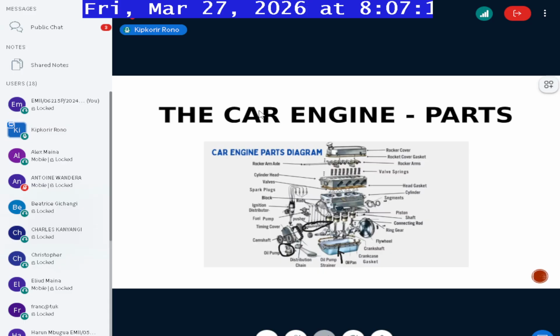Number two is that the oil usually settles at the bottom of the engine. Okay? With the oil reservoir. So if you were to just switch on your car and move, some parts of your engine could be oil starved, all right? That oil starvation is not very good, okay? So you usually have to let the car allow the oil to circulate for a few seconds or a minute or two, because in any case it is usually very highly pressurized, so it will move in very quickly within a very short time, it has circulated,